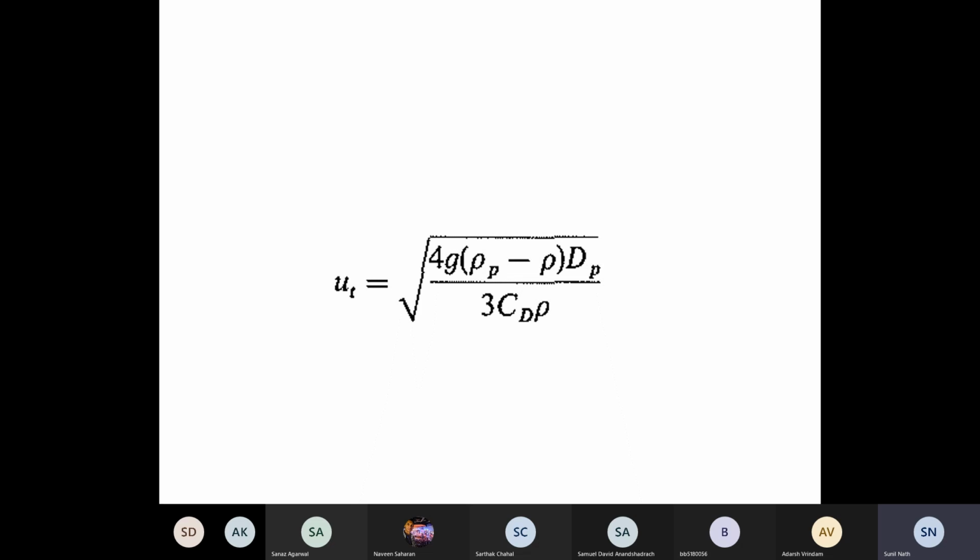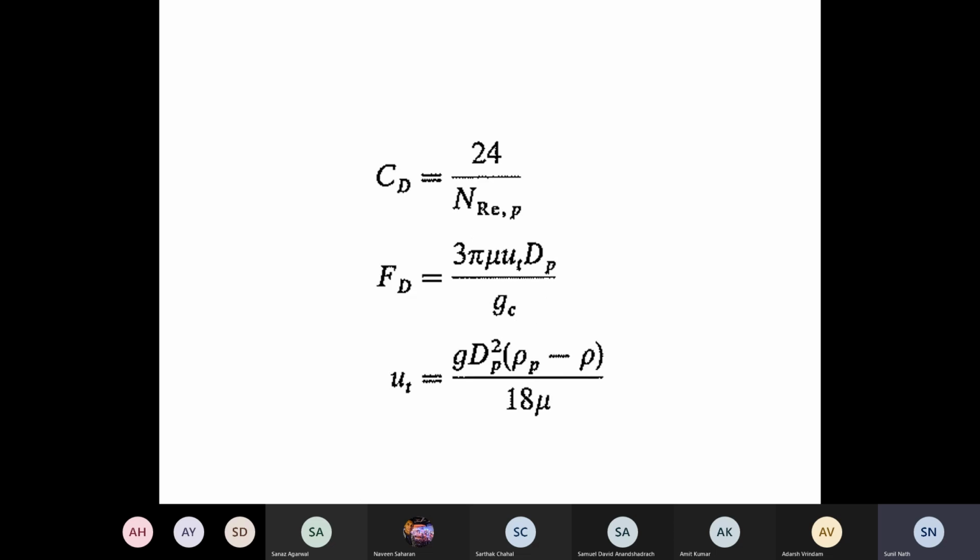So essentially, what you had to find out is the constant which brings the Reynolds number and the CD value, and the inverse proportional dependence of CD on RE, which is the hallmark of that region, right? So at low Reynolds number, the drag coefficient varies inversely with the particle Reynolds number, and the numerical value was 24, right? So please see that you should all derive these three relationships. The bottom one is what we started out with, okay? So please do that.